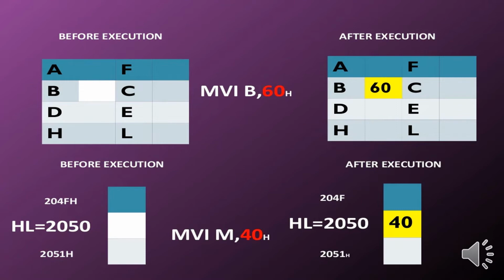In this way we can directly transfer the data into a destination register or destination memory location. In the move immediate instruction, one of the operands is 8-bit data, so we already know the value and can send it directly into the register content or memory pointer.